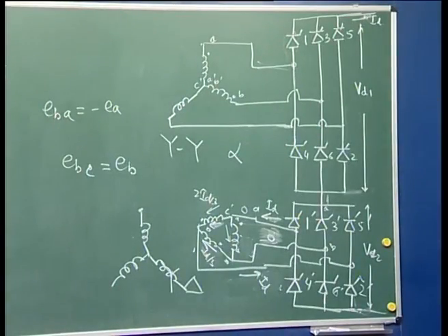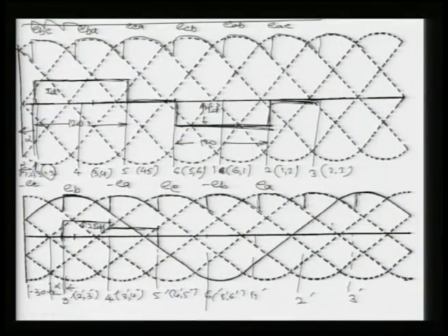So, we are going to have the same magnitude here, and up to this it will be conducting. So, it is your ID by 3 on the negative side we have drawn, and again if you go further you will find it is 2 ID by 3 here, this is your 2 ID, then again you will find ID, and again you are going to have this current here as well.